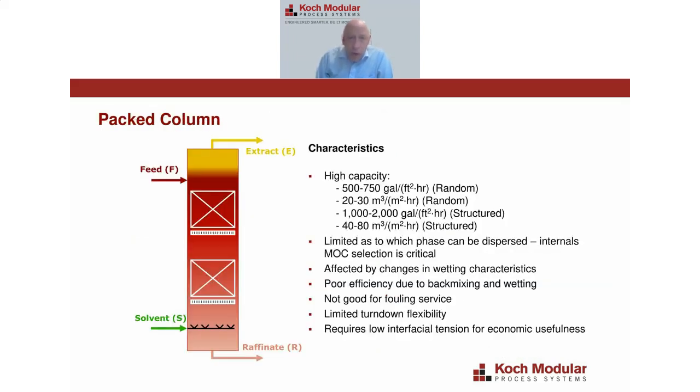So we're going to, again, focus primarily on the column type contactors, and certainly a packed column using random packing or structured packing is often used for liquid-liquid extraction. I do not believe there's any difference in efficiency between random packing and structured packing for liquid-liquid extraction processes, and I haven't seen data to really prove there is. That's because in extraction, we're really not trying to form films on our surfaces. We're trying to form droplets. And then we want those droplets to stay as droplets and flow countercurrently.